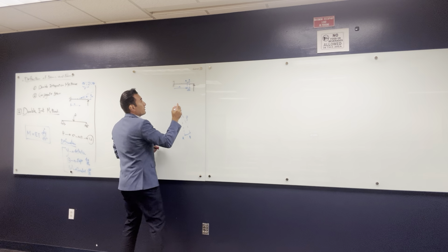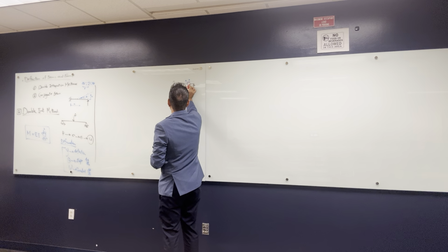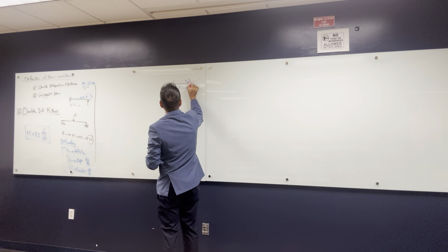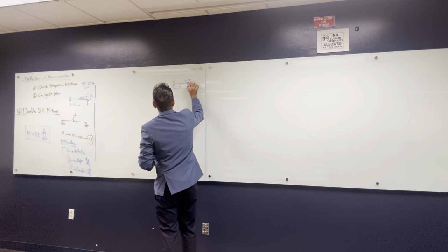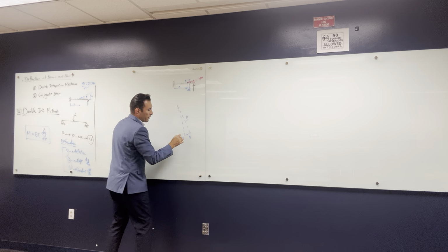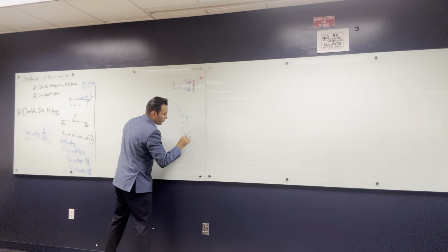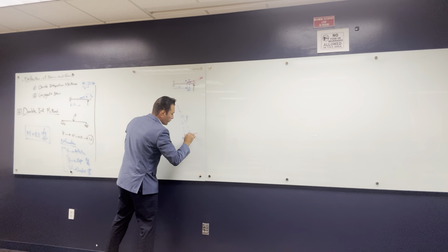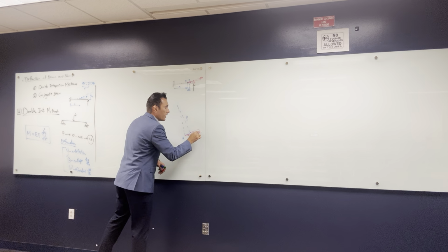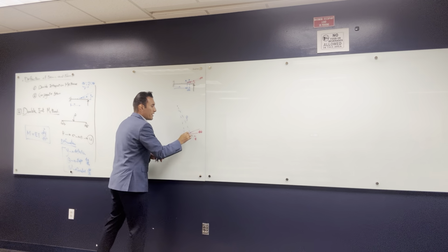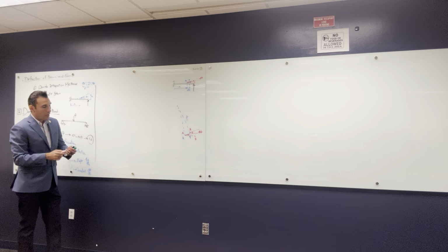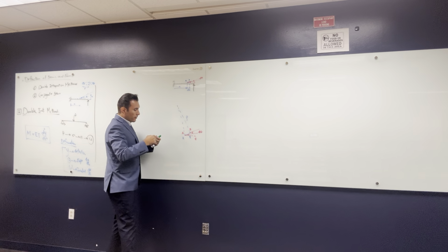The slope at point A: you draw a horizontal and one that is tangent at A, and this is theta. You can do another one at B, and the difference between the two angles is d theta. So this is theta, which is the slope at A, and d theta, which is the difference between the slope at A and B. This is d theta.